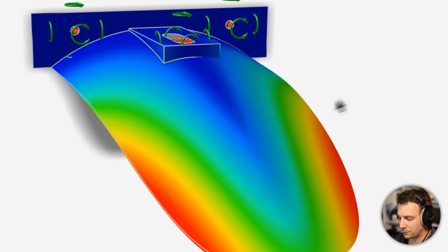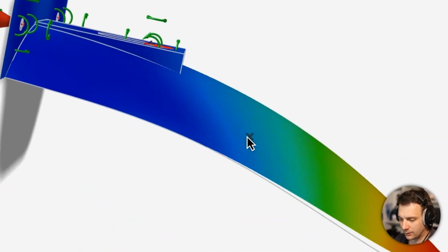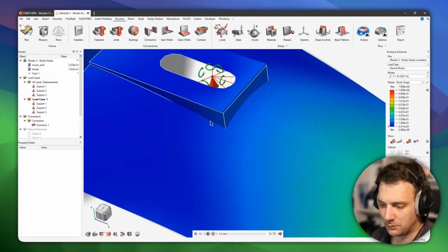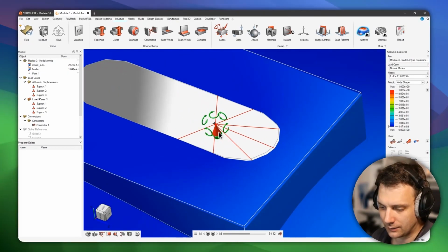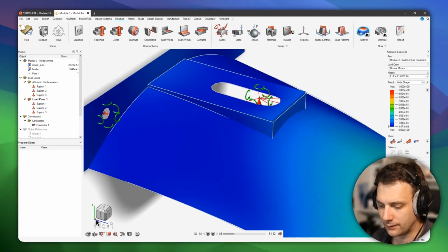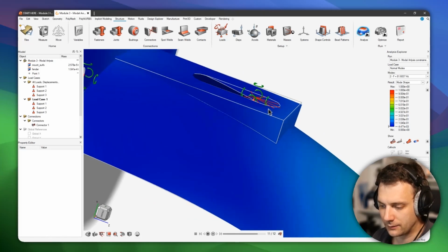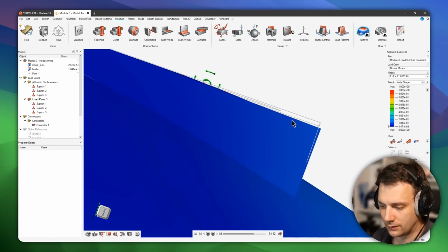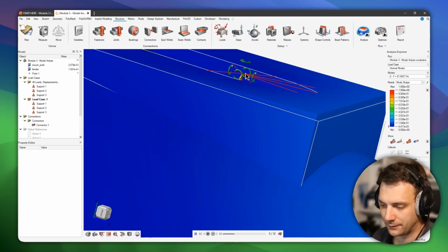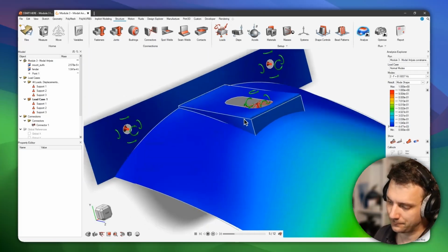All right, so this would be the first mode. If you go to the second mode, you have another mode, which you could also imagine is a realistic mode. And you can also see this bearing is moving in the Z direction, right? So you can see that it is working, and it's also turning a little bit. You can see it's going up and down. This point cannot move up and down, but as the rotation is free, it can turn or tilt.